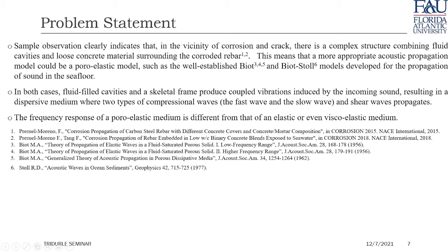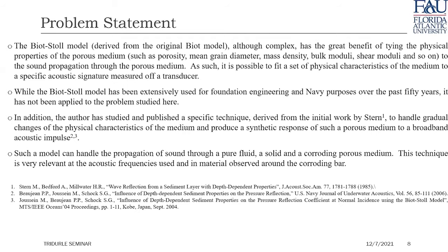So in both cases, fluid-filled cavities and the skeletal frame produce coupled vibration induced by the incoming sound, resulting in a dispersive medium, which means that the response of the medium depends on frequency, with two types of compressional wave, the fast and the slow wave, and a shear wave. The frequency response of a poro-elastic medium is much more accurate than what would be obtained using an elastic or viscoelastic medium, which are usually the models used with techniques such as finite element modeling and other techniques, ANN, CNN, and so on.